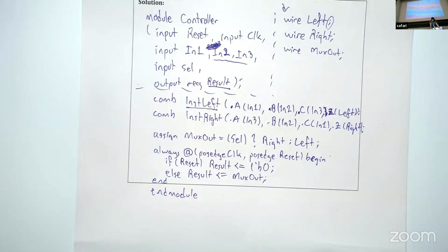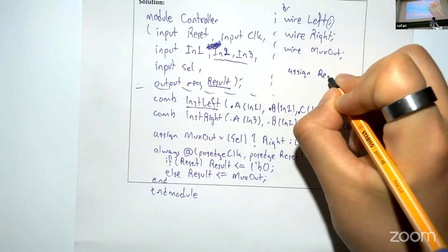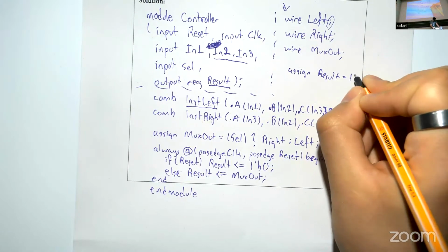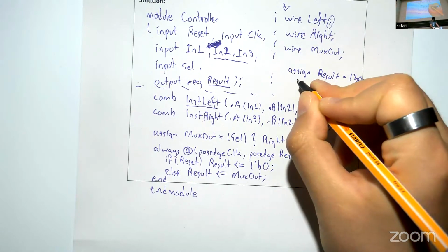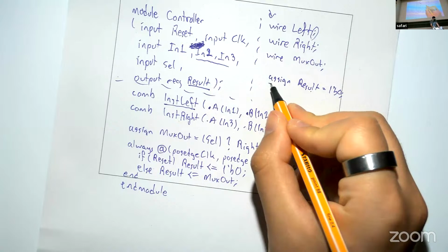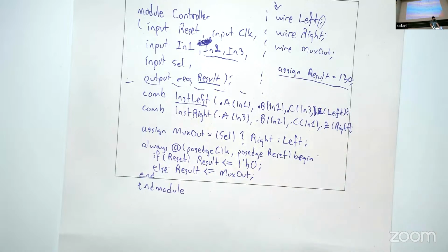You can still define it, but you cannot make an assignment like this to result right now, because it's not a wire. So this statement would be incorrect outside of an always block, this is just an example. Right now you cannot do this, but you could have result and not have anything assigned to it as well. I think Vivado or your compilation tool would eventually warn you or lead to some sort of error, but you can have it. Yes.